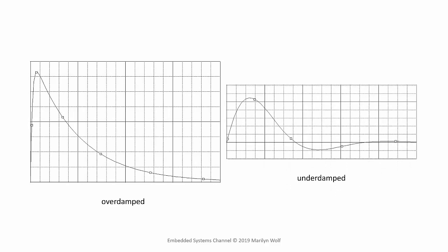We can classify RLC circuits into two different categories depending on the balance between their different component values. In the overdamped case, we see that the response goes up and then asymptotically approaches a final value. In the underdamped case, we see that it oscillates toward convergence to a final value. There is a third critically damped case, which is just at the razor's edge between these two cases.